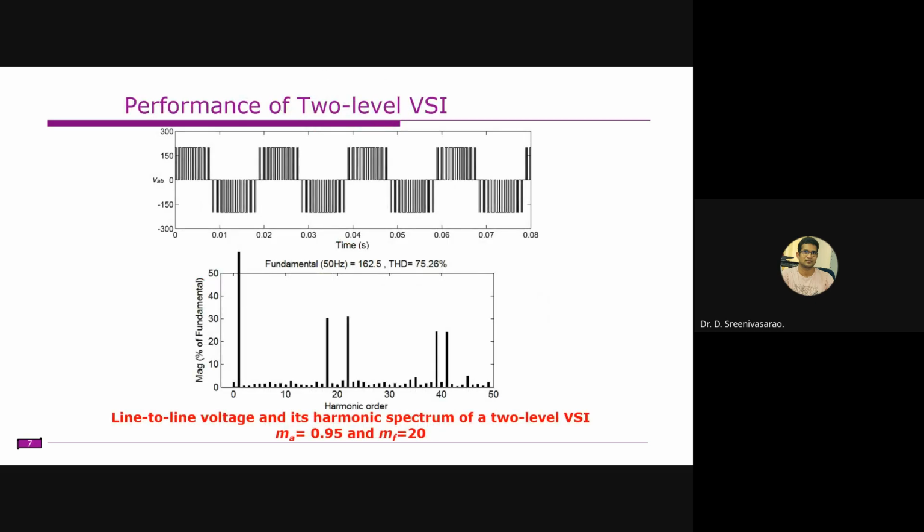Most of the time, to control these inverters, there are two PWM control methods: one is the current control method and the other is the voltage control method. In the voltage control method, you require a modulating signal and some carriers. By comparing the carrier and the modulating signals, the switching or firing signals are generated for each phase, and the inverter will operate as a controlled voltage source.